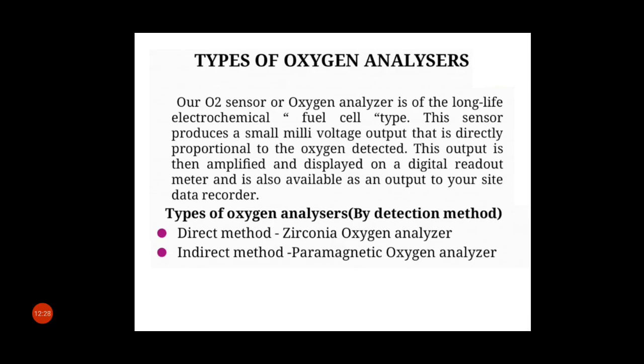This sensor produces a small millivolt output which is directly proportional to the detected oxygen. This output is then amplified and displayed on a digital readout meter and is also available as an output to our site data recorder.